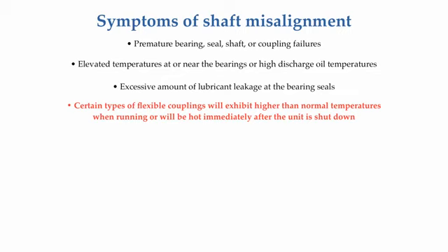The motor was again started, ran for 15 minutes, and another thermal image of the coupling was taken. This process was repeated several times, where they kept adding 10 more mils of shim stock under all of the motor feet. In some tests, they installed 30 total mils of shims, and on other tests, they installed up to 40 mils of shims. After one coupling was run through all the varying amounts of controlled intentional misalignments, that coupling was removed and a different one was installed for that coupling's battery of similar test runs. Here is what they observed.